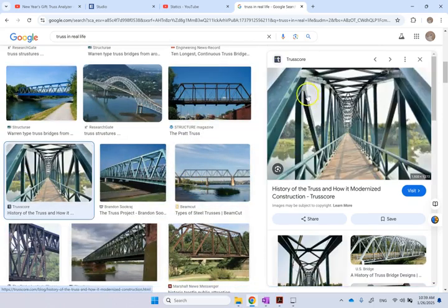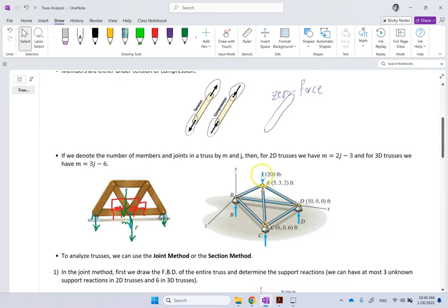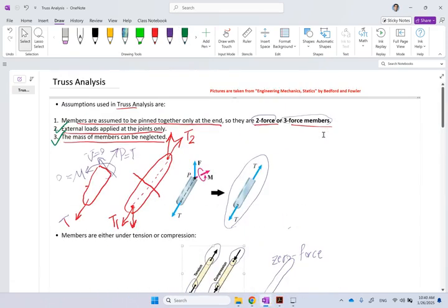But in reality, you never see the members being pinned together. They are always these brackets, and they are kind of pivoted. There are rivets, and there is not one, there are several. So you cannot really say that's a pin, because a pin should allow a rotation, and there is no rotation anywhere here. So if that's the case, then you have to analyze what we call the machines, okay? And that is one of my future videos.